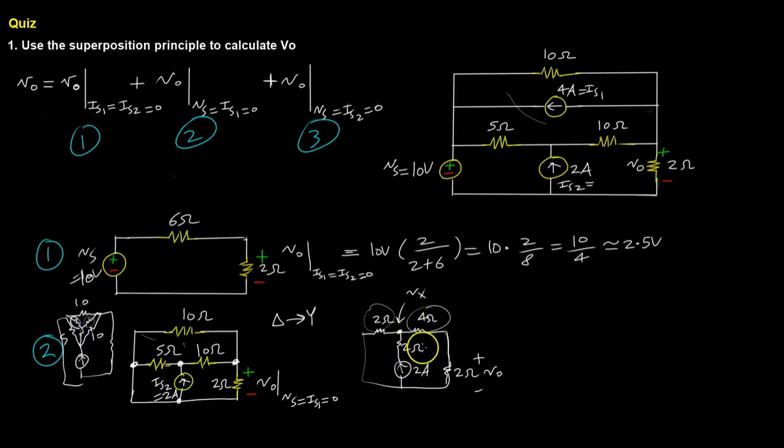So I've gone ahead and done that, and once you do that, you see a current source going up here to this particular node. I'm going to call that Vx, and I'm going to do a simple KCL. So I'm going to say that's the current going there, and going there, these currents. And if I do one KCL equation, I get that, now this is Vout when Vs equals 0, equal to Is1.